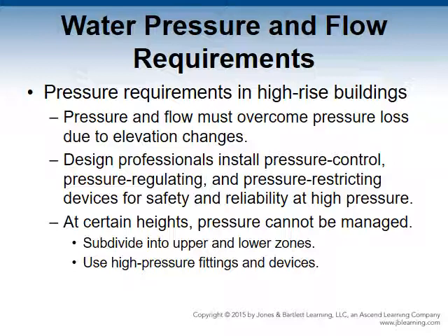Design professionals install pressure control, pressure regulating, or pressure restriction devices to overcome safety and reliability issues that result from such high pressures. Devices may be set up at a factory or in the field, but either way, they must be calibrated to avoid putting occupants and first responders at risk. At certain heights, it is no longer practical to manage such high pressures.